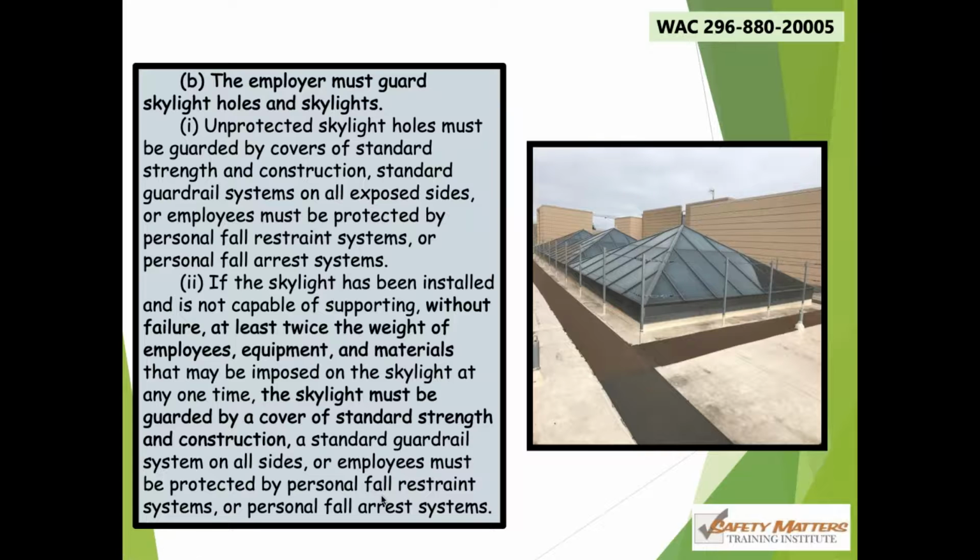Skylights, you guys are up there on the rooftops. So if we're working on roofs and there's skylights or open holes where the skylights are supposed to be, these things need to be protected so we don't fall into them. If the skylight has been installed and is not capable of supporting, this is new right here, strength requirements in big bold letters is new, without failure, at least twice the weight of the employees, the equipment and materials that may be imposed on the skylight at any one time.